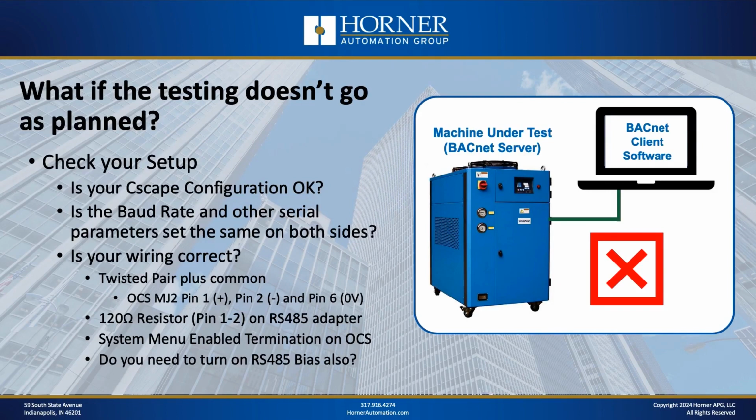So that means pin 1 and 2 on that port are connected as plus and minus. All right, and pin 6 is your common, which is always a good idea to run if you can. And of course, the pinout on the 485 side, on the computer side, is going to vary based on the adapter you have.